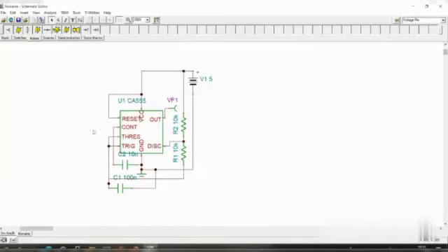And if I need to check the capacitor voltage again, the capacitor voltage will have a very large influence on the multivibrator. So the capacitor voltage you can find, this capacitor voltage, not this capacitor, this capacitor, that is the capacitor voltage, we will say VC. So to find the capacitor voltage, we can connect either to the trigger point or to the threshold, both are connected to the capacitor, and this resistor is also at the same point.